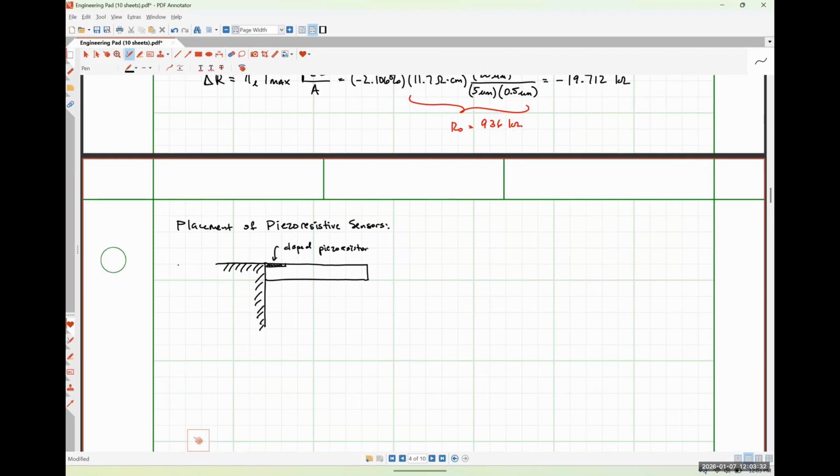which shouldn't be particularly difficult, because if we're starting with a semiconductor-based beam, we would just dope it as part of the manufacturing process, either through ion implantation, diffusion, etc., all of that kind of good stuff. We should be able to control the thickness through all of those parameters. Or the other option would be to deposit it on the surface of the beam. So something akin to this.